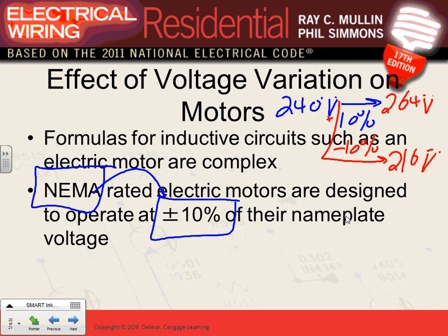Because you can't maintain a constant voltage, guys. Voltage is never constant. We have a nominal voltage for calculation, but the actual voltage always fluctuates. If the air handling unit runs right now, the voltage will go down. Shut down the air handling unit, the voltage goes up slightly. So the smart manufacturers have to allow this fluctuation, plus or minus 10%. I want to remind you that's the extreme situation, but what does the code allow? Anybody remember what the code allows?